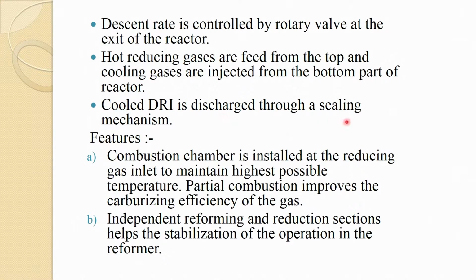So, cool DRI is discharged through a sealing mechanism. Combustion chamber is installed at the reducing gas inlet to maintain highest possible temperature. Partial combustion improves the carburizing efficiency of the gas, and independent reforming and reduction reactions help the stabilization of the operation in the reformer. So, these are the features of HYL process of fluidized bed one.